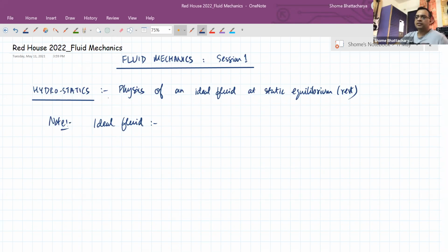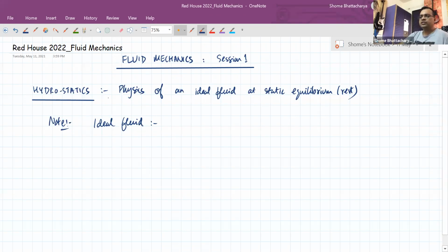So that is what we mean by the first property of ideal fluids, that it is incompressible. And the second property is that we'll assume an ideal fluid is non-viscous, or in other words, that any type of viscous force is absent. So viscous force, as you might have heard, is the equivalent of friction in fluids, but it is not called friction, it is called viscous or fluid drag force. And like kinetic friction, it is a non-conservative force that opposes relative motion.